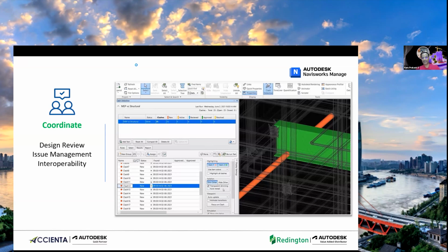If you put a pin on the steel there, it will trigger in Navisworks exactly where the issue is, who is working on that issue, and what needs to be done. Is any RFI required? The same thing can also be pointed out in Revit. So the coordination will happen without a phone call, without a lot of email communication, and without a lot of WhatsApp chat. We eliminate all of those, and we can be on the same page to give the best design out of this in the federated model.